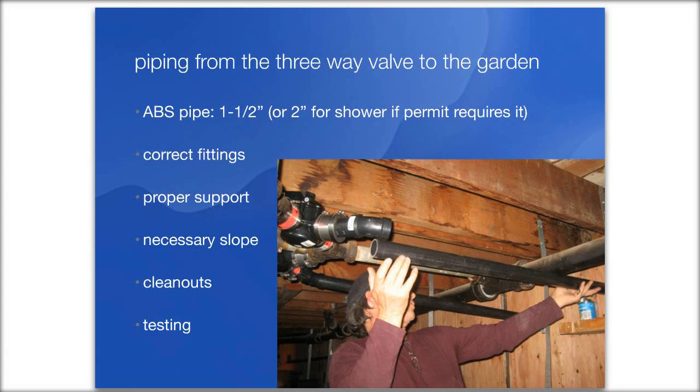I don't know, it could be in a closet. You'd frame out an area in the slab that would be open on top, so you would have permanent access to that valve. Any other ideas, Laura? A cost issue. If it's cheaper to do it that way, do it that way. Or if it's cheaper to just run the pipe outside, out underneath the building or outside in the ground, you would have the access area. I think it's possible running it outside is better, but yeah.